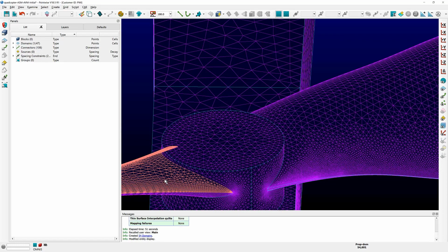With the mouse pointer right there, you can hit the space bar and you can see that now the lower surface has been pre-selected. So I can hit the control key and left mouse button again. At this point, the upper and lower surfaces have been selected.